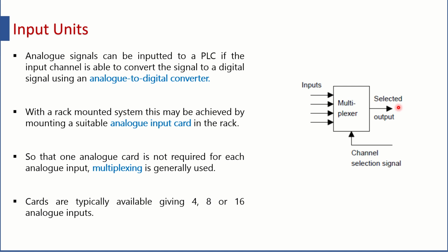Now you see how much synchronization of time is required, because if this signal is continuously changing, then to what extent are you going to keep this particular channel latched over here? That signal is going to the analog to digital converter. Many a times it happens that the analog to digital converter is not that fast at which this analog signal is changing. So accordingly you need to design certain sort of buffer, latch, all these circuits.